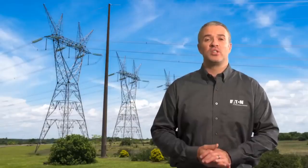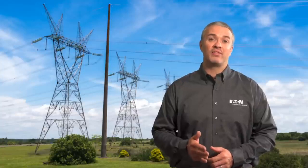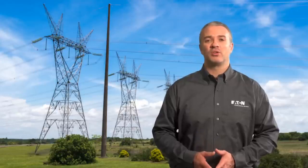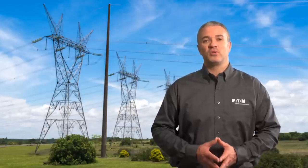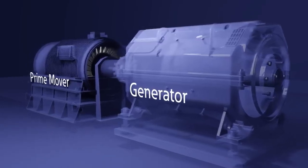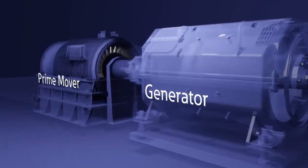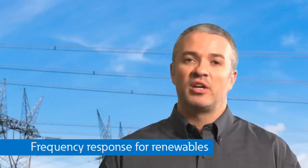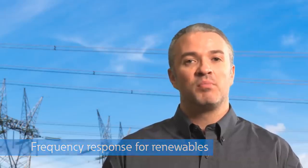Even with large fluctuations in load, large utility generators don't allow the frequency to change much because they are large rotating masses and provide significant inertia to the grid. This is extremely beneficial to the grid by stabilizing the voltage, but it could take up to a minute for these units to get frequency back to the proper level if something catastrophic happens because they are so large. Some widespread blackouts have been related to significant frequency changes in the response of large generators and groups of generators. Wind and solar have a much faster frequency response due to the use of electronics, but they don't provide as much grid stability provided by large generators with rotating inertia.